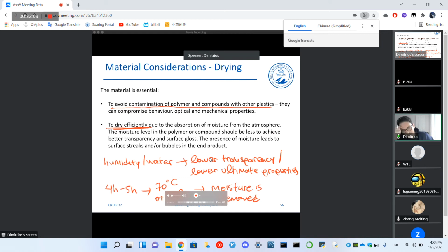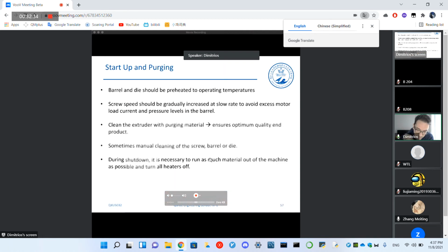Of course, we could reach, I don't know, 100 degrees, but 100 degrees several times for thermoplastics can be close to either their melting points or the glass transition temperatures, and we don't want to be within temperatures that are close to these significant thermal transition temperatures in order to keep our material unaffected before extrusion. These are too technical, not too important. Don't pay too much attention to these.